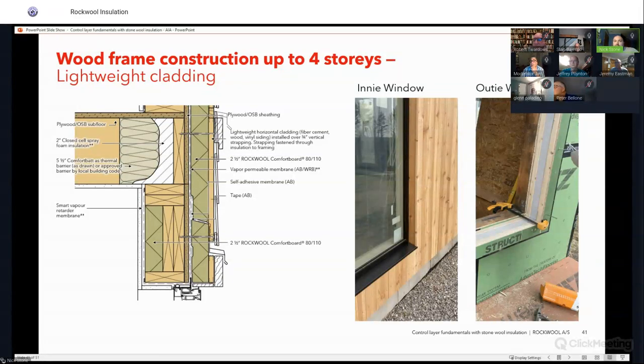It's probably pretty beat up. Again, continuity, I apologize for saying it so many times, but because it's no longer a square bat like this, it's compressed, it's kind of broken down. You're just not holding enough R value there anymore. So by putting in a new bat that can hold its rigidity over time, it's going to keep that continuity, that consistency of high R value, versus what's there, which is probably degraded and broken down. If it's fiberglass, it 100% was broken down and needs to be replaced.